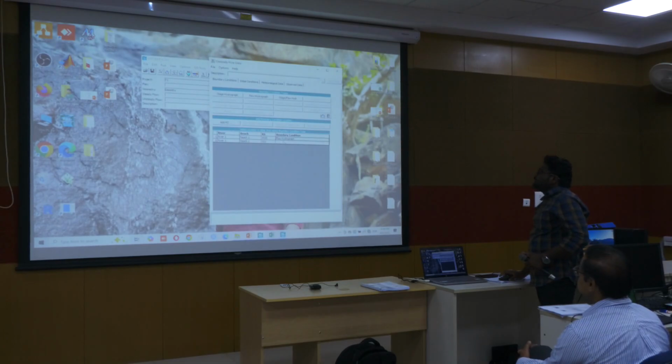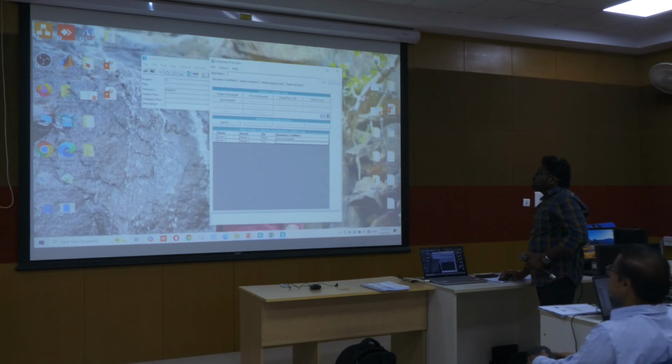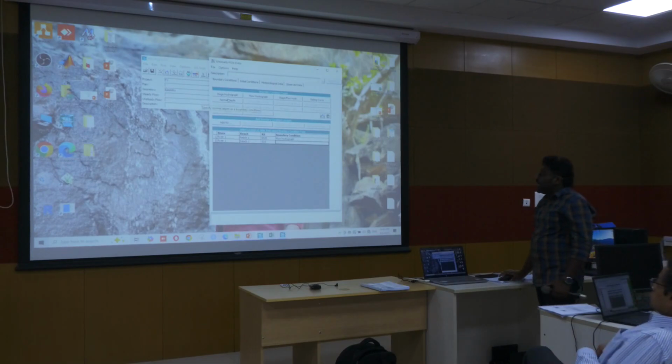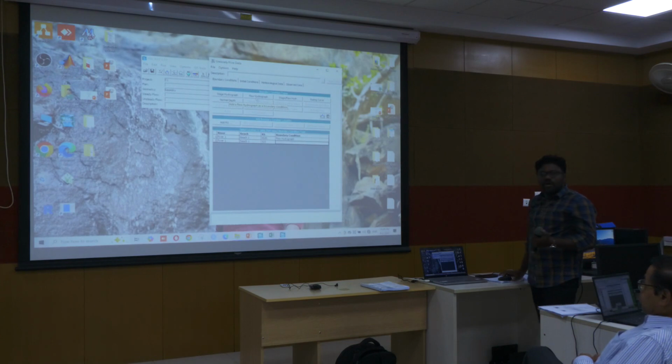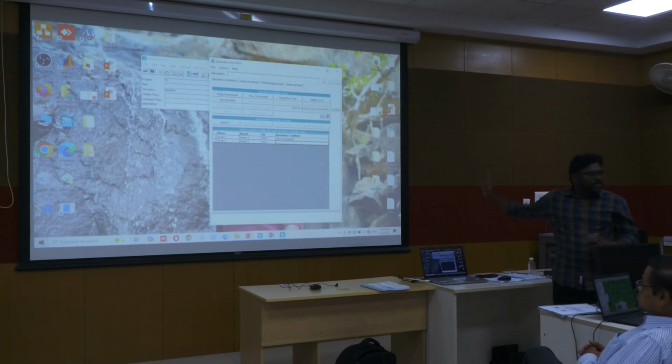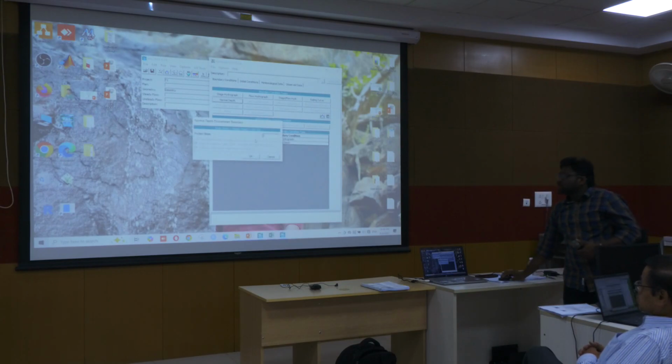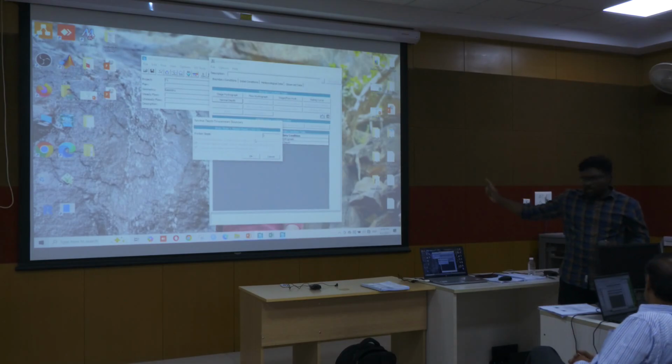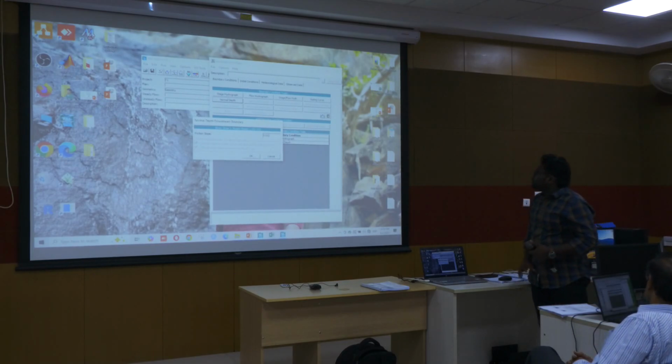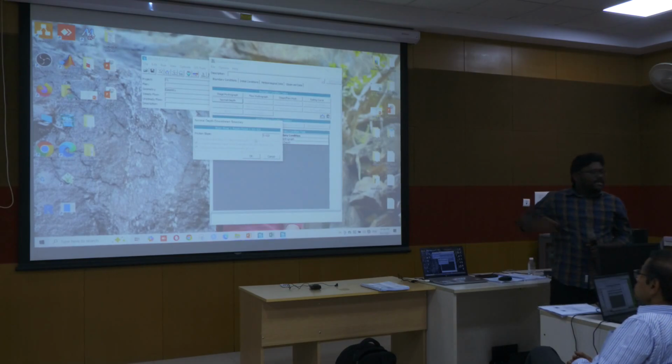Okay, you just click here. Normal depth. Click on normal depth. I told you, right? At the downstream, if you have the stage hydrograph, you can give a stage hydrograph. If you have the flow hydrograph, you can give that. But as of now, we don't have the water surface level or the flow hydrograph at the downstream, so we are going with the normal depth concept. If you have rating curves, you can also give the rating curve. Normal depth will ask you to mention the friction slope. Just mention 0.02, which was the average slope.